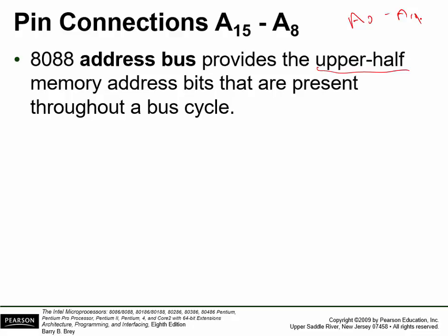Now, as I mentioned before, modern processors have almost 1,200 pins. They don't bother multiplexing, because multiplexing means you have to slow down to put the address out first, latch it, then put the data out separately. So it requires additional bus cycles. Modern processors just put more and more pins on there. They made the chips bigger and bigger. Actually, they're not very big. I took one out the other day, and you saw even with 400 pins, it's still not much bigger than these old 40-pin devices.